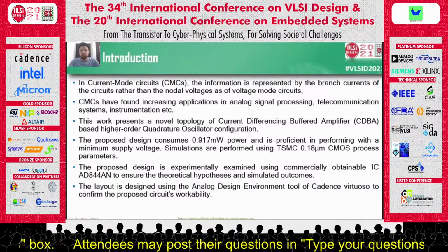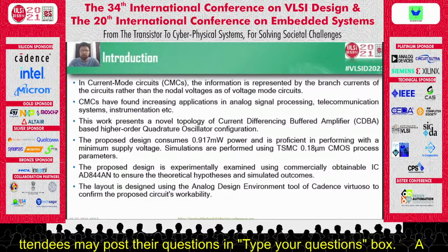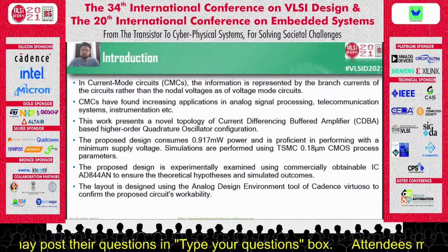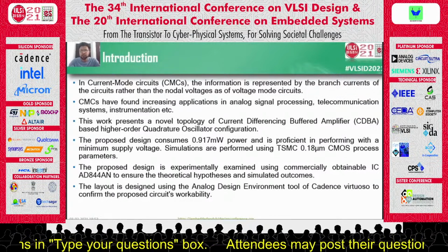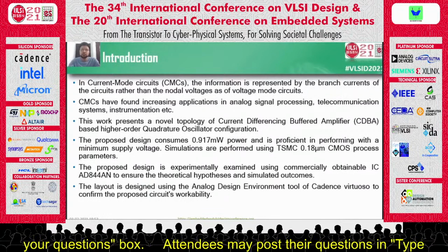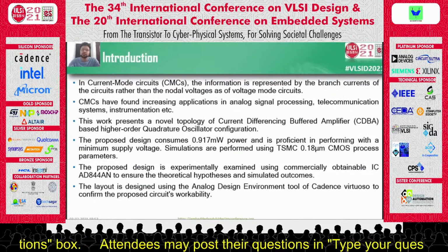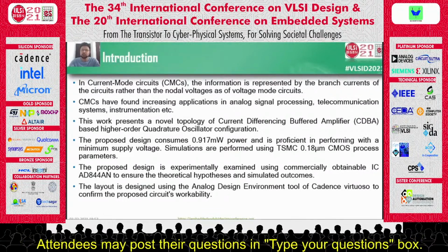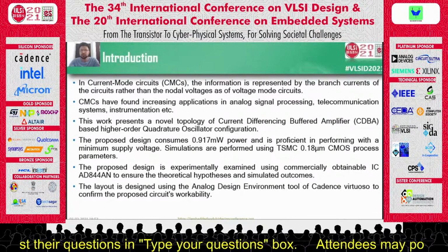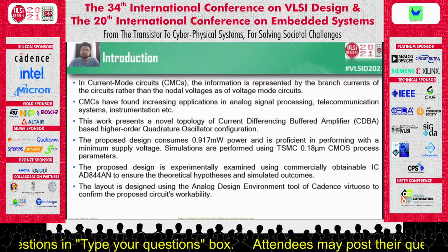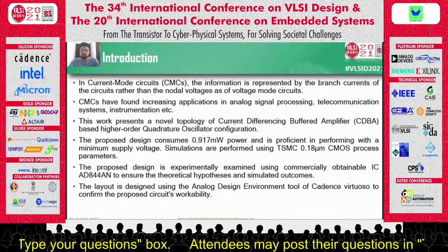Introduction. We know that voltage mode and current mode are the two regulating conditions that control the output of a power supply. In most of today's applications, the call is for a supply to be used in voltage mode. In voltage mode, the power supply provides a constant output voltage while providing the required current to the load. But in current mode circuits, the power supply provides a constant current to a variety of load voltage conditions. So these two regulating modes work to provide constant control of the supply.